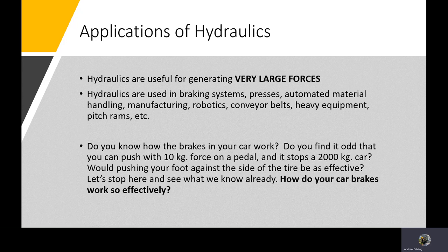So if you're ever wondering how you can push with 10 kilograms of force on your brake pedal and it stops a 2,000 kilogram car, if you were pushing on the side of the tire, there's no way you would be able to control that much force to stop the car. But by using hydraulics, we can use these multiplication factors to make the system much more efficient, and you get a lot of output for very little input.